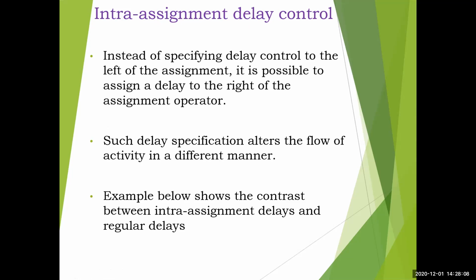In the delay-based timing control, the first one was regular delay control. Now this is intra-assignment. This is the same as in data flow modeling. We have learned continuous assignment statement and intra-assignment statement, something internal, right? So that is equivalent. Instead of specifying delay control to the left of the assignment, it is possible to assign a delay to the right of the assignment operator. So we have two types of assignment operator, right? Equal to or less than equal to.